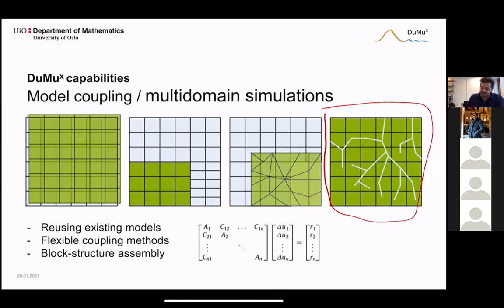And then you could solve some equations on each of these grids, on these systems separately. And then what Dumux gives you is the necessary tools to now find, for example, for this segment here, which 3D elements do I intersect with? Or maybe if I have this kernel method and I want to distribute it in a region, it's some more cells, so it helps you doing that.